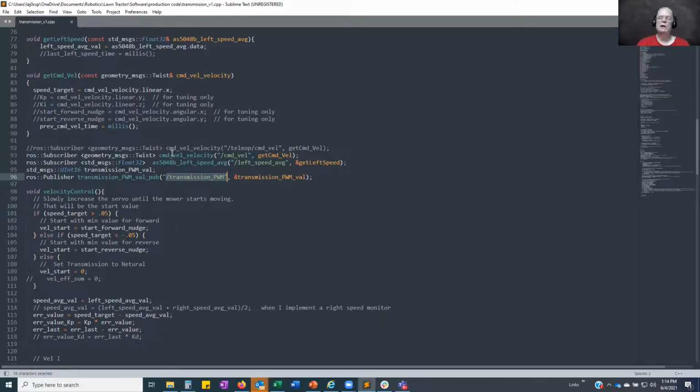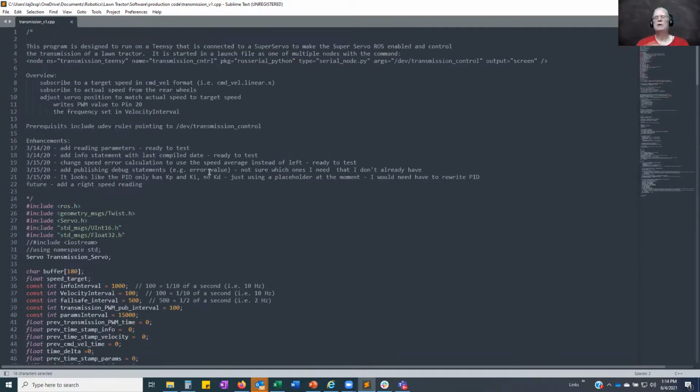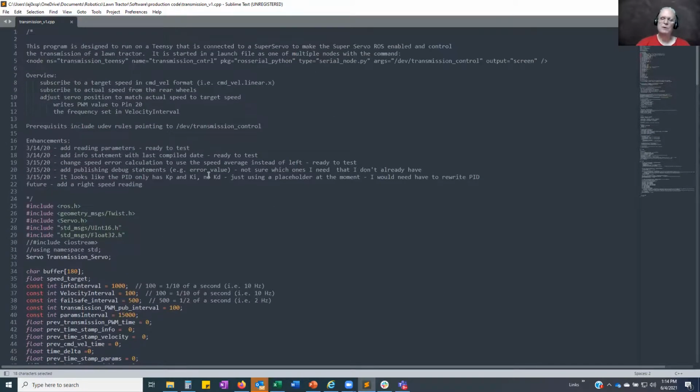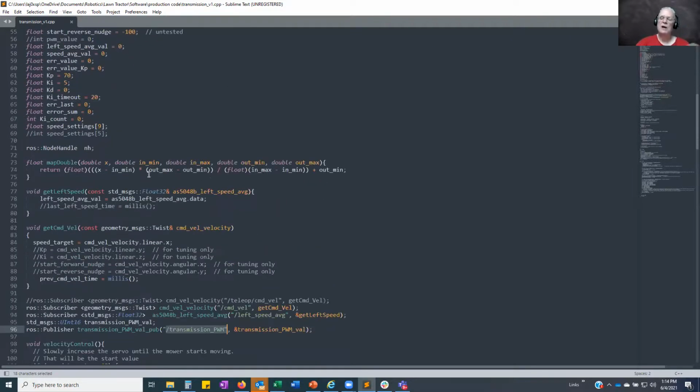Well, we're not looking for that kind of detail. We want to know, in order for ROS to talk to your external device, when people wrote up ROS serial, they created a node that runs under ROS, and it connects over USB to an Arduino, and then they talk back and forth over that interface. So the question was, if I have multiple Arduinos plugged in on separate USB ports, is the ROS serial node that runs under ROS smart enough to know you've got multiple devices plugged in?